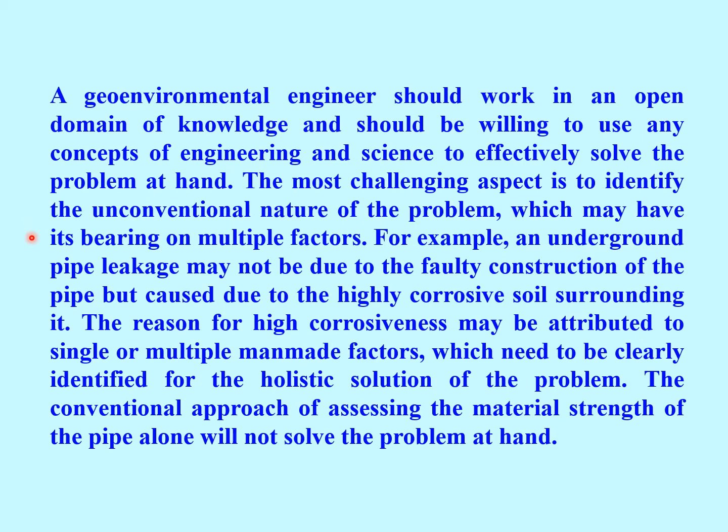For example, an underground pipe leakage may not be due to faulty construction of the pipe, but caused due to highly corrosive soil surrounding it. The reason for high corrosiveness may be attributed to single or multiple man-made factors which need to be clearly identified for the holistic solution of the problem. The conventional approach of assessing the material strength of the pipe alone will not solve the problem at hand.